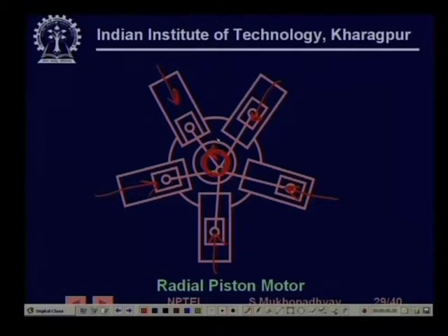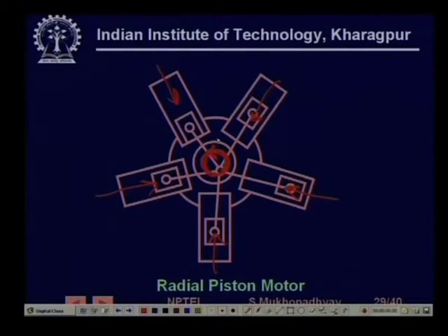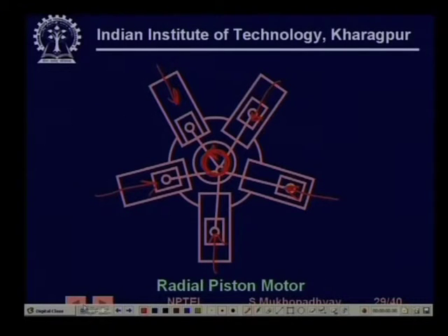So, this is naturally of a positive displacement type, that is, in every cycle of the piston movement a certain amount of air goes through the system. Similarly, you can have non-positive displacement type. Here we have not shown a figure, but it is exactly similar to the vane motor of hydraulic systems in principle, although there may be constructional differences in design.